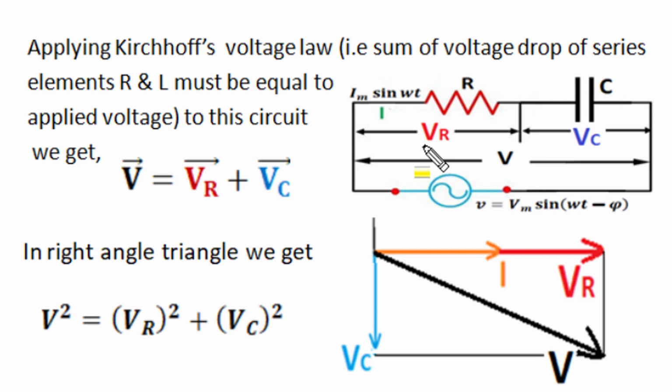As per Kirchhoff's law, in this RC series circuit, the total applied RMS supply voltage across the RC series, in phasor value, is the phasor sum of the voltage across resistance and the voltage across the capacitor. And we know when current is taken at horizontal reference, the voltage of resistance, V equal to IR, comes in phase with circuit current, and voltage of capacitor, V equal to IXC, lags current by 90 degrees.